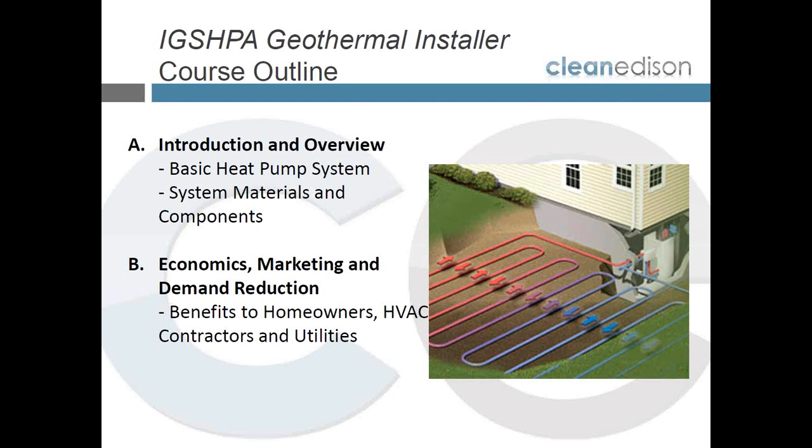And the temperature differential here is about 5 or 6 degrees. Believe it or not, water that's entering the house at 45 degrees and leaving the house at 40 or 39 degrees, that 6-degree differential divided by the gallons of water that are required are enough to provide the total heat that's needed for the building.